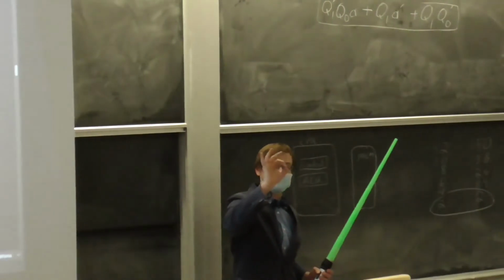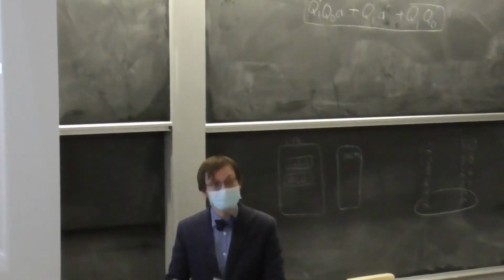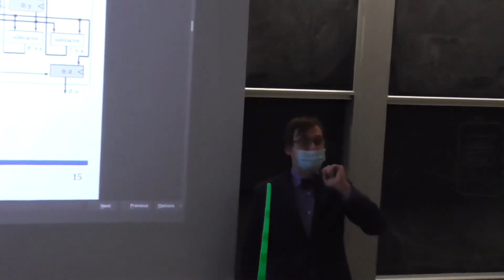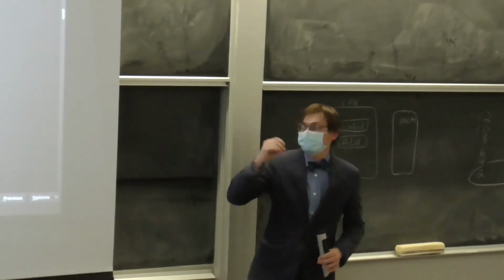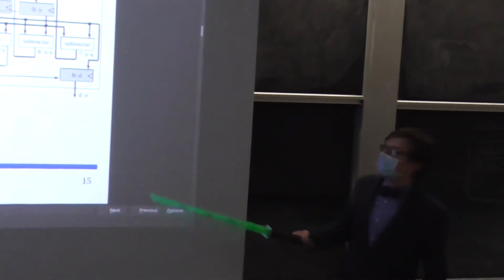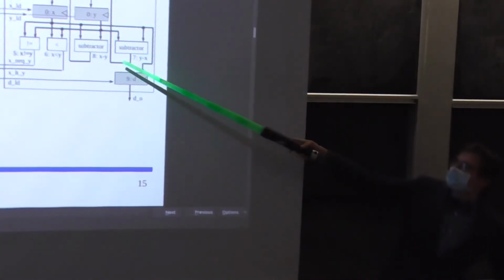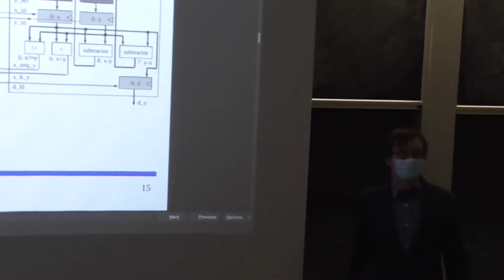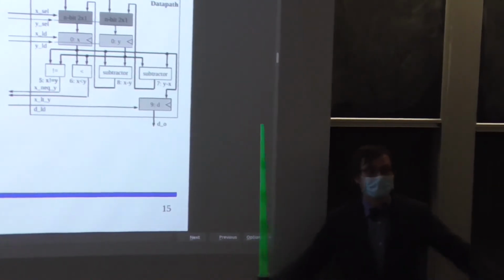When you design the instruction set, what you are designing is which of these modules you want in your ALU, right? You can imagine, the more of these guys that you include in an ALU, the bigger the multiplexers have to be, right? Because they have to feed more things. It just makes the circuit larger.